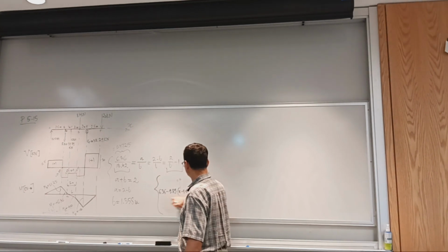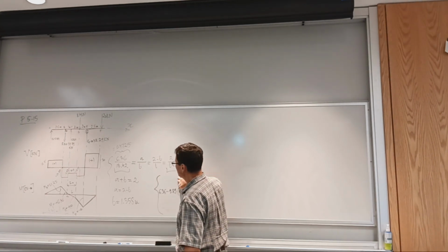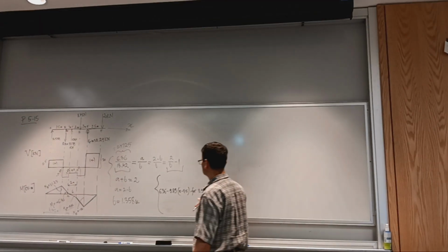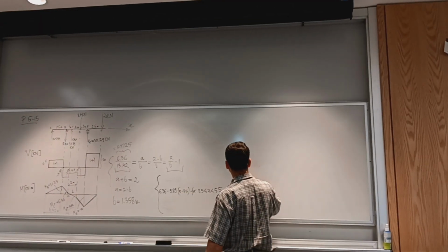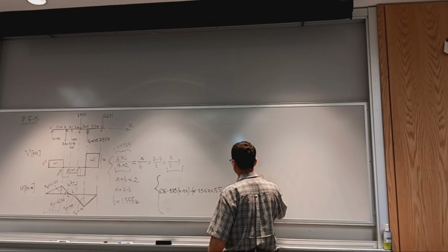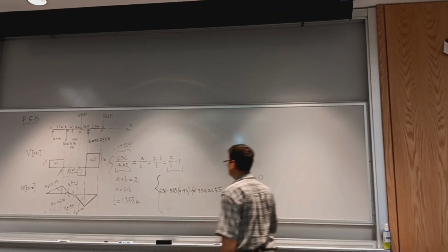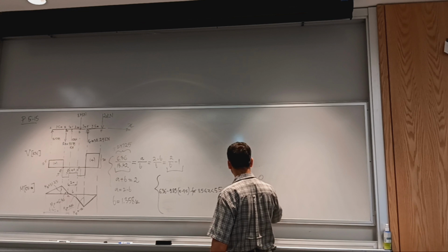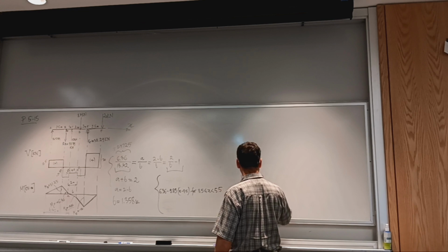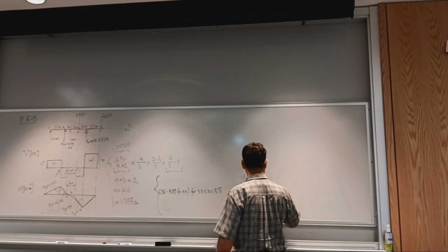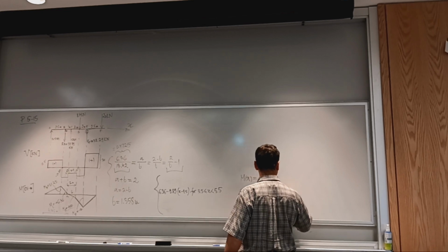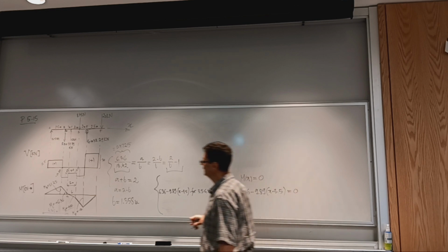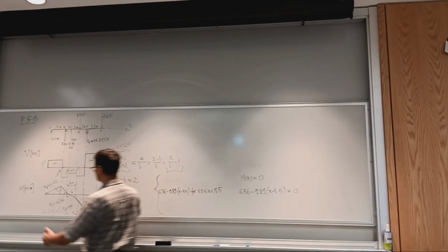So we have the equation of the moment between points C and D, and now we can just set it equal to 0. So M of x equals 0 for the right piece of it. So it will be 6.36 minus 9.89 times x minus 3.5 equals 0. And x is going to be actually directly this value.